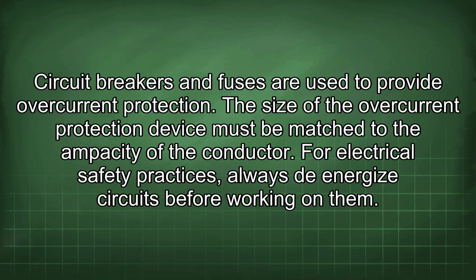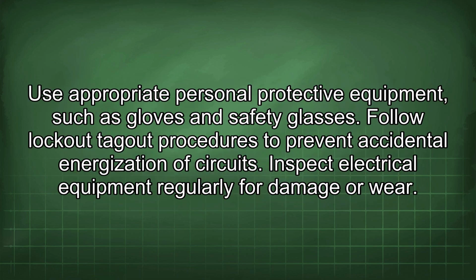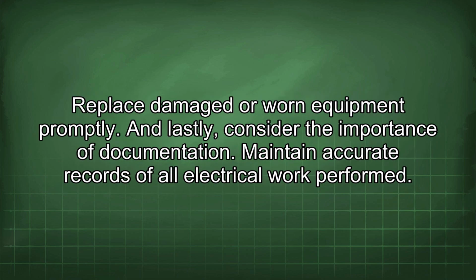For electrical safety practices, always de-energize circuits before working on them. Use appropriate personal protective equipment, such as gloves and safety glasses. Follow lockout-tagout procedures to prevent accidental energization of circuits. Inspect electrical equipment regularly for damage or wear. Replace damaged or worn equipment promptly.